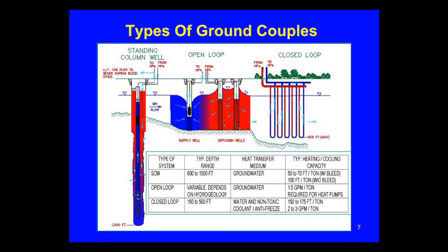When you pump that water up and you change the temperature, you're creating a disequilibrium with those minerals and chemicals that are in the groundwater. And when you put the water back into the ground at a different temperature, that creates a problem, because you tend to have things like scaling. You have precipitates